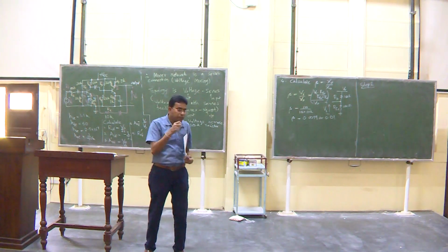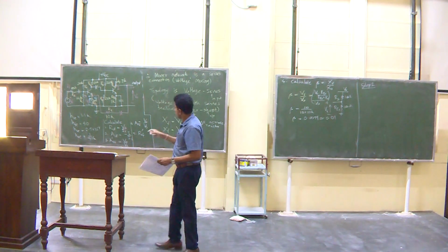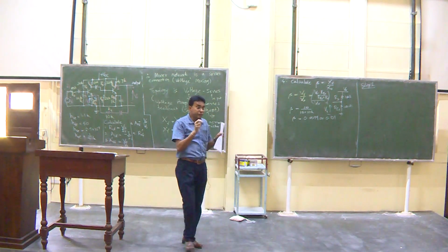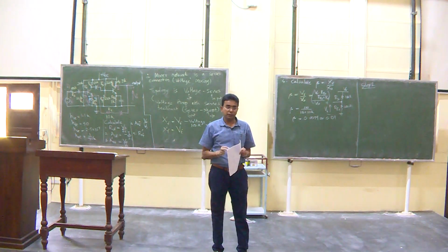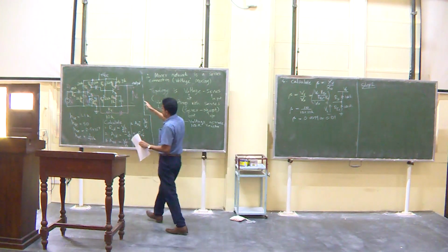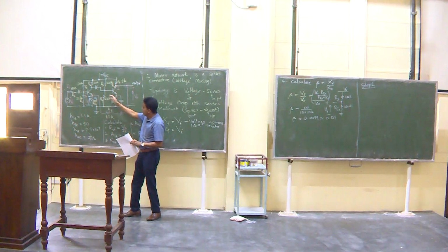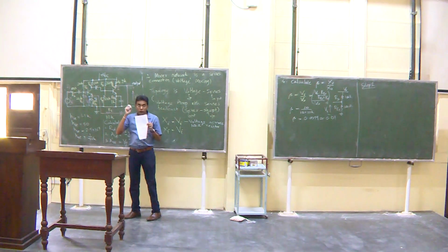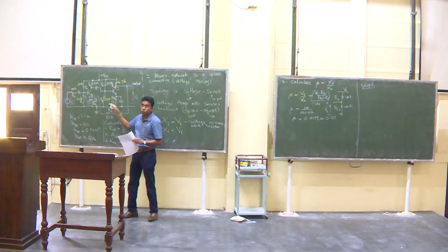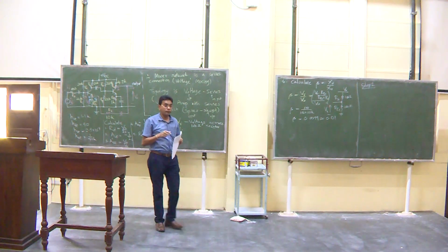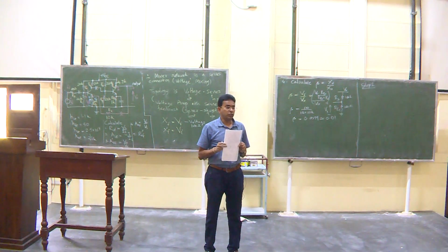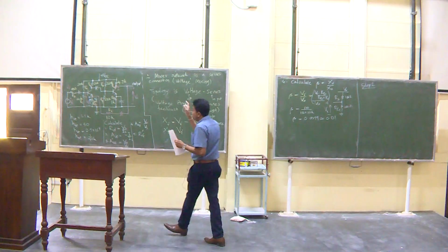So, therefore, in the next step we are going to find the circuit without feedback, but with the effect of loading due to the feedback network. Okay? So, the important step is removing this RF, but removing it in such a way that we still keep an eye on how much current goes through this and how much current goes through that at the input and output. That needs to be carefully controlled. Okay? So, with that we are going to draw it.